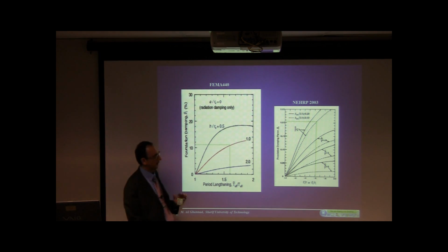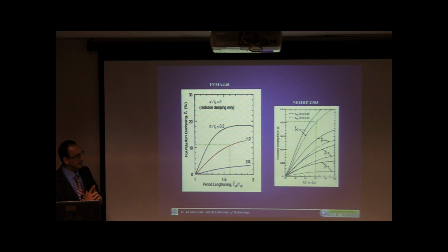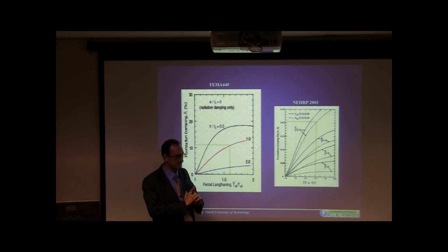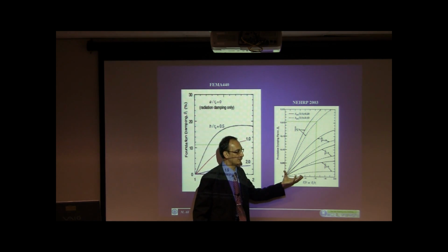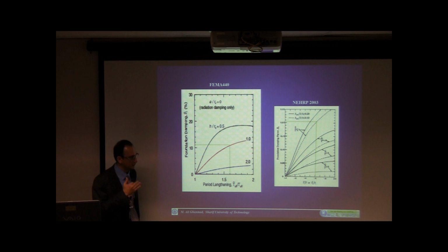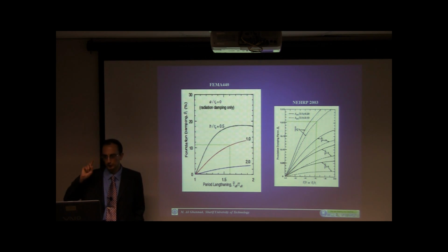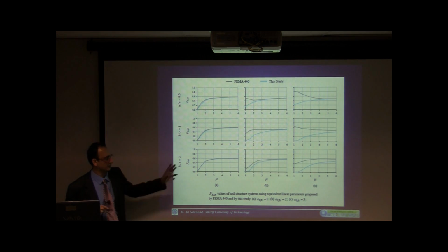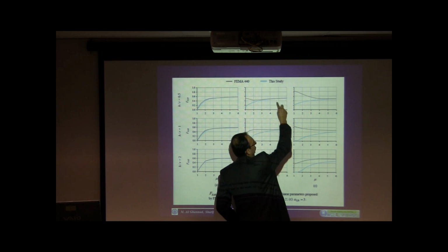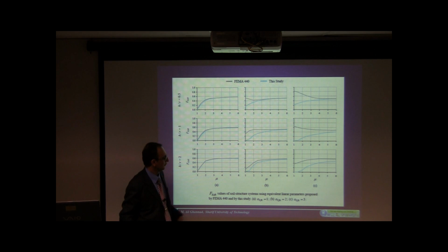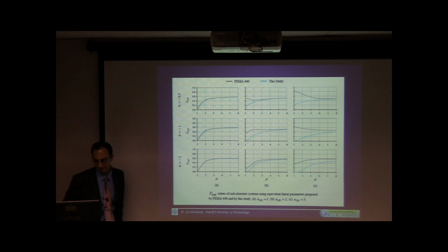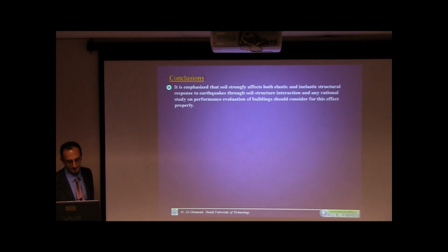And it means that the damping ratio presented in FEMA 440 is less than those already existing for the elastic cases. And probably, I think, they reduced the damping to get better results for higher damping ratios, and they were successful in that because we have very good results for the higher ductility. But for the near elastic cases, the results are almost overestimated. Okay.